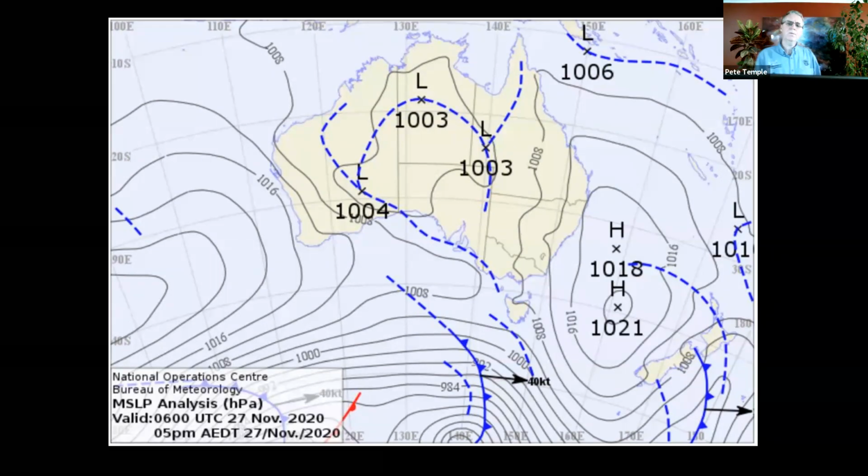In days past, we'd look at this synoptic chart, or prognostic chart. We'd look at forecast maximums from the Bureau of Meteorology. We'd look at observations, in particular the atmospheric sounding. So that's the sounding of the temperature and the dew point of the air and wind with altitude, and use some heuristics and basically guess when the thermals were going to start, how strong they were going to be, where the best regions would be to fly. It's way easier to do that than it used to be.